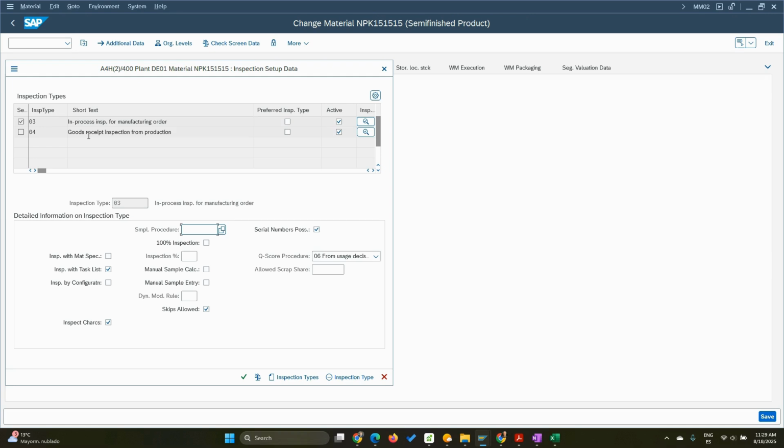Okay. There is another reason, which is basically when you need to confirm the operation, right? For example, for some important addition of raw materials, before loading that raw material, like I mentioned before, you might need to check the pH, for example, right? Or if the temperature is fine or not.